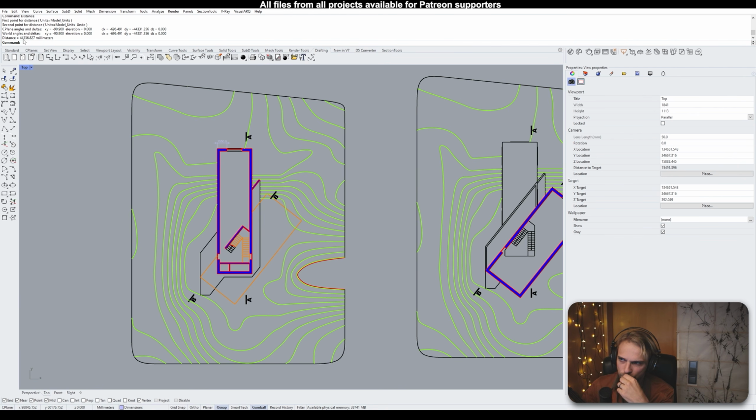244 meters. So for 44 meters, 1 to 100 becomes 44 centimeters. And 44 centimeters doesn't fit inside of an A3, but almost doesn't fit, because A3 is 420 millimeters in length.